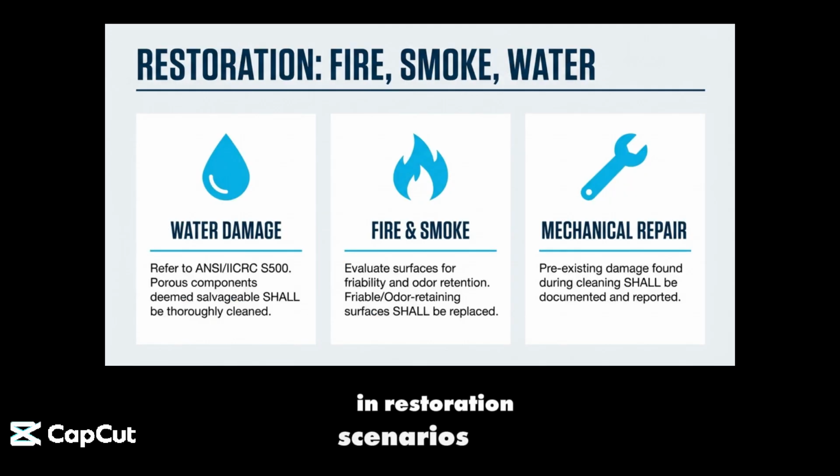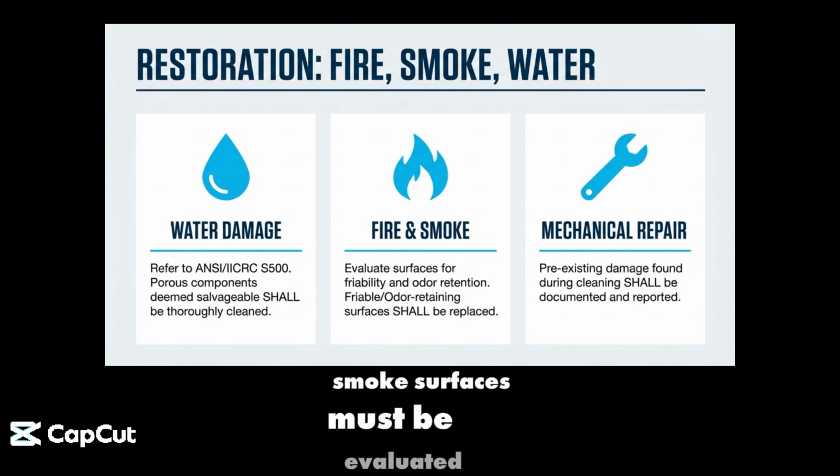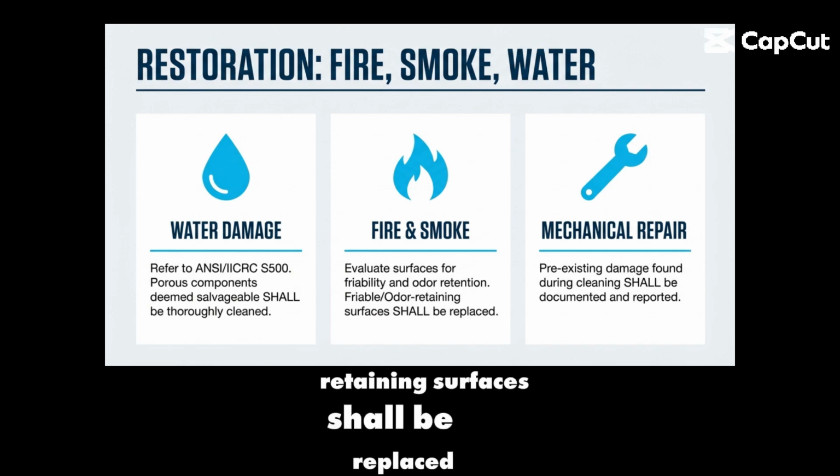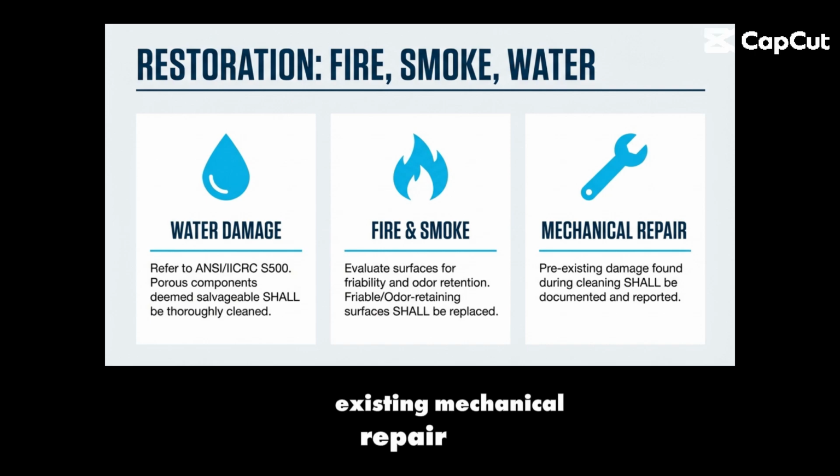In restoration scenarios, water damage adheres to the ANSI/IICRC S500 standard, where salvageable porous components shall be thoroughly cleaned. For fire and smoke, surfaces must be evaluated. Friable or odor-retaining surfaces shall be replaced. Any pre-existing mechanical repair needs found during cleaning shall be documented and reported.